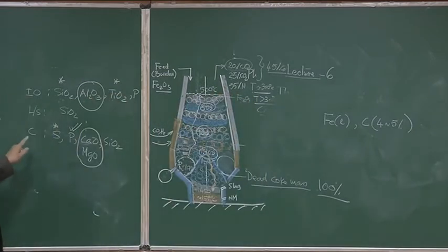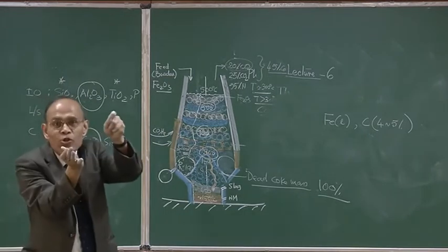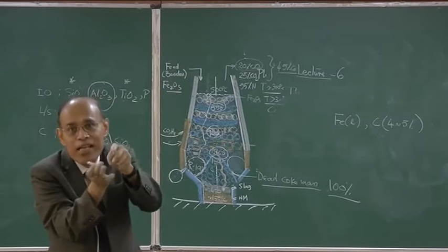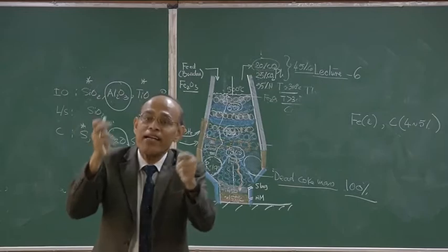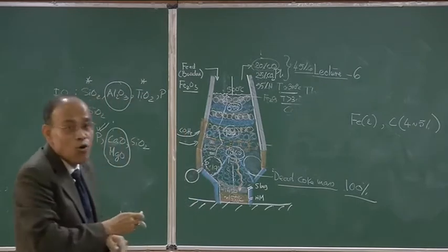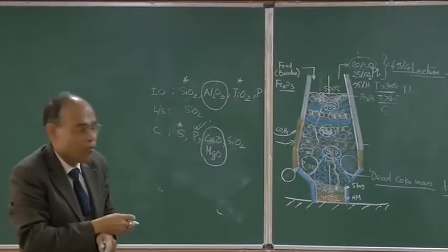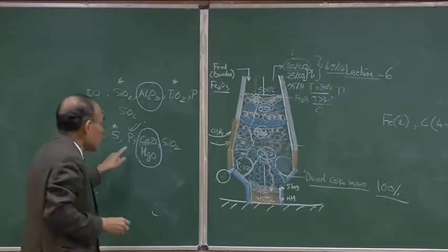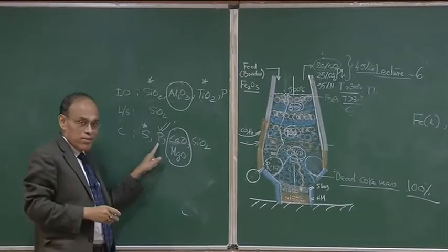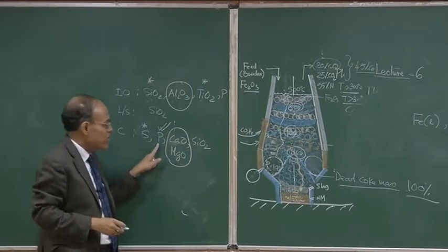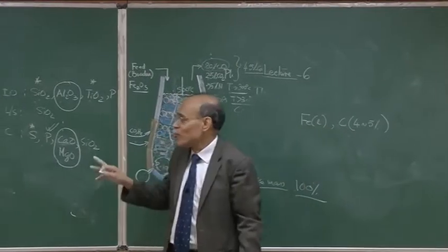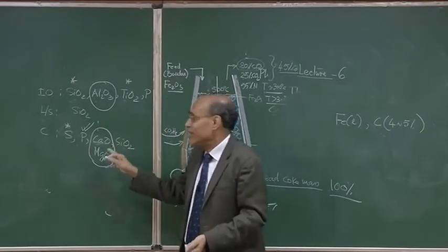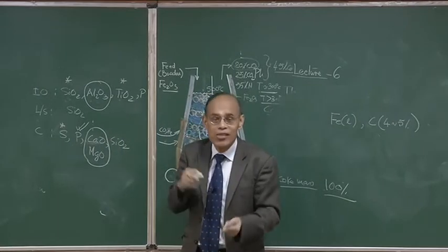Now, about phosphorus, for example, if you look at the Ellingham diagram, the phosphorus pentoxide line and the Fe-FeO line are absolutely close, which essentially means that if an environment and temperature can reduce FeO, that will reduce phosphorus pentoxide within the furnace. So, we can say all those elements which are reduced in the blast furnace are going to go into the metal phase. All those elements which stay as their oxides will remain in the slag phase. So, there will be a combination.